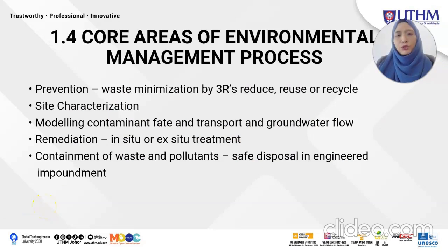Okay, now we proceed with the core areas of the environmental management process. The first one is prevention, by using the 3R concept: reduce, reuse, and recycle. Second one is site characterization, so we need to identify the contaminants that appear at the sites. Third one is modeling contaminant fate and transport and groundwater flow. This one we can apply by using software.